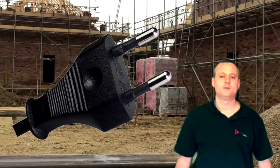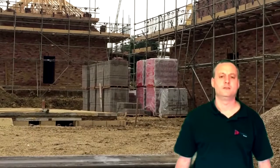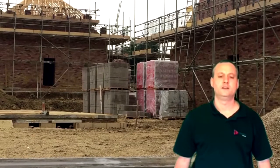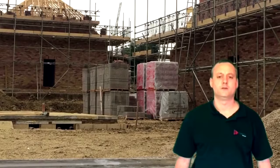The transformer that supplies the actual shaver socket itself is also an isolating transformer. Therefore, no connection to earth on the outgoing side. Therefore, no risk of shock on the outgoing side to earth.